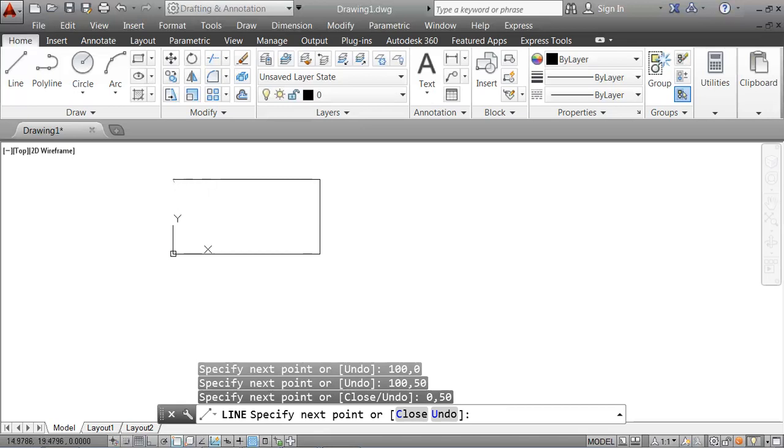Now you want to go to this point here. You might remember that this point was 0, 0. But let's do the calculation, right? Where we are now, we are at 0 in X and 50 in Y. We want to go down 50 millimeter. Because you are at 0 in X, you're not going to be moving more than 0 or less than 0.